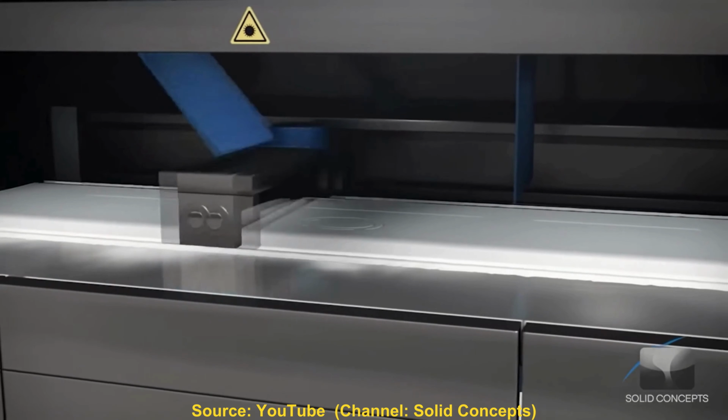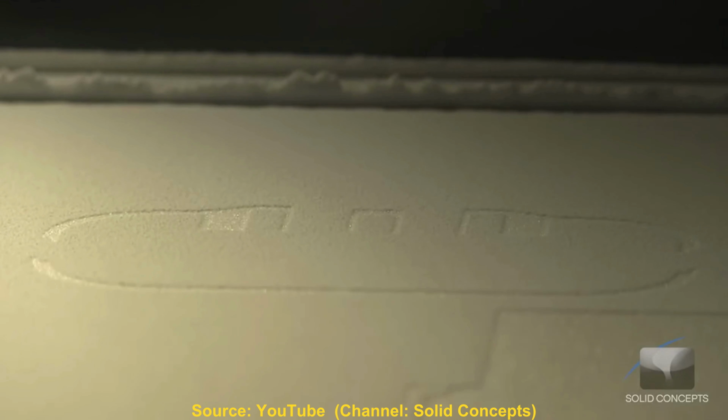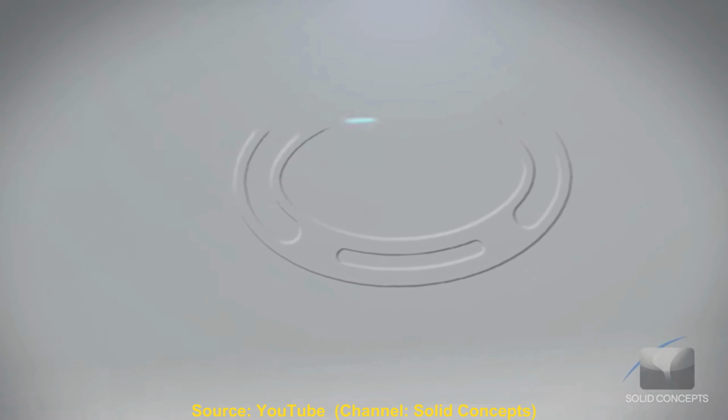This video shows the powder bed fusion process. A thin layer of powder is prepared before each layer is scanned by the laser. After completion of the fusion process by the laser, the next layer is deposited by the recoater mechanism. And the process goes on till the last layer.